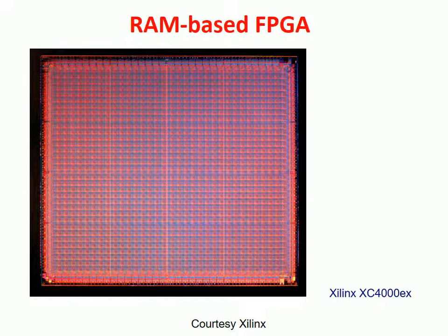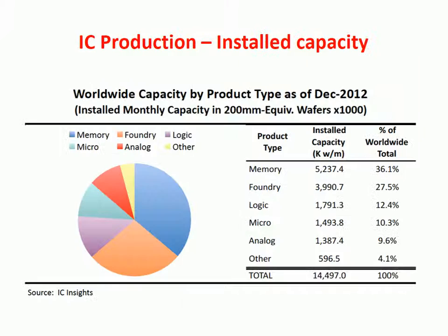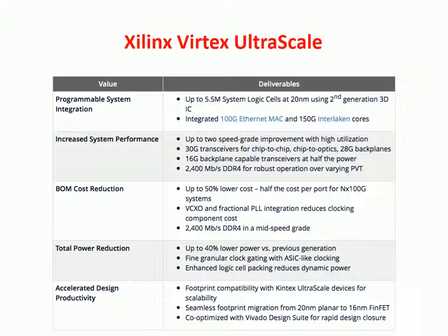Okay. The SRAM-based FPGA is much more regular. As you can see, in this case, every small square in this example is a small combinatorial function with an attached memory to be programmed. So every small combinatorial network, every logic gate is obtained by programming an attached memory. Okay, we can stop here.